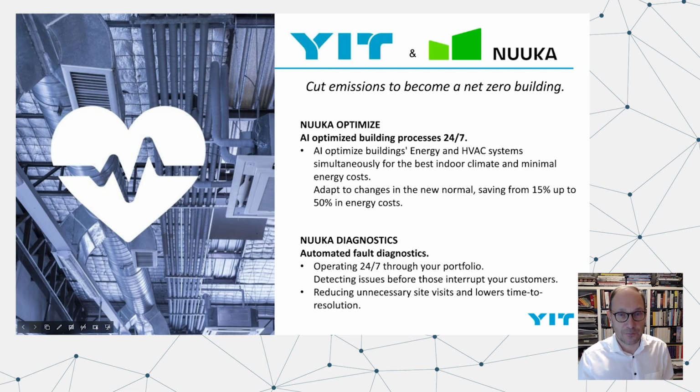The other part we use Nuka for is that it integrates with the building automation system and pulls the data into PropTech OS, where all the data from the different sensors are. It has built-in 170 different cases of faults, and through PropTech OS we automatically push fault indications to the facility management system Granlund Manager, and this way we can do predictive maintenance of the HVAC system. We can read off different energy meters, and all of this data is then displayed to the building owner as well as the facility manager through easy-to-use user interfaces.